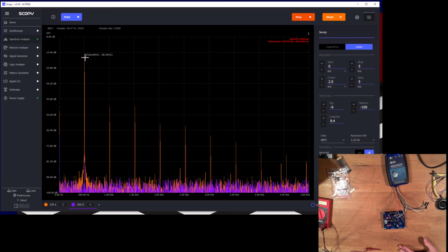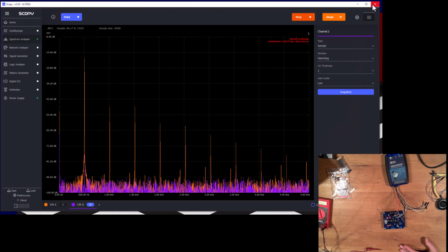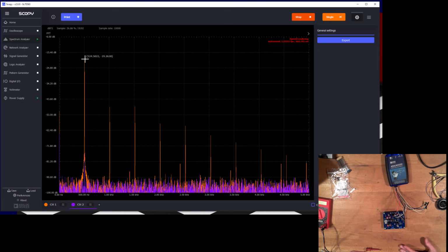And then let's get an idea of what our THD, our distortion, is. It looks like this isn't measuring. This doesn't do a direct measurement of distortion, but that's okay. We can just sort of mentally see how far down we are. So here we're at about -18 and about -47.